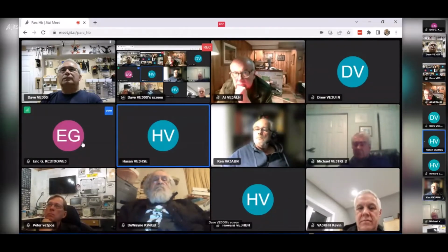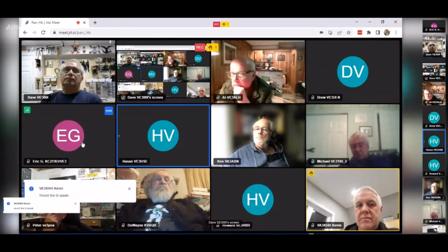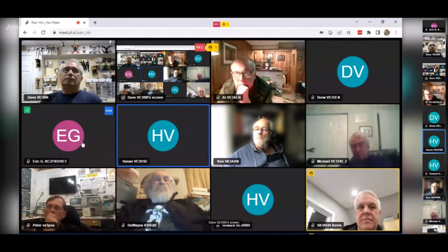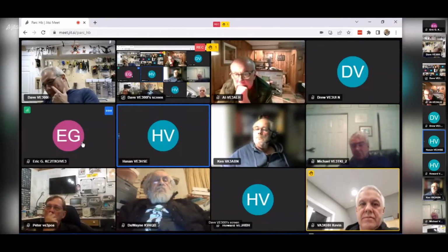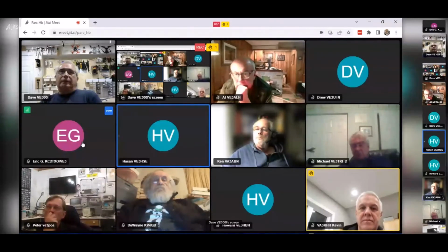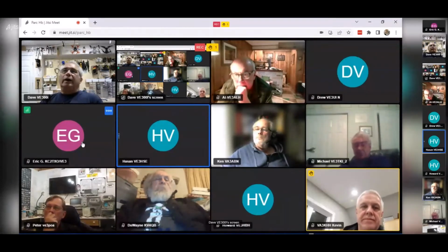And so maybe you're just pulsing it too fast, and it's burning power in the drivers. If you used, like, I don't know, 1,000 steps per second, that might have been good enough. You would have got the same result, but a lot less power, and probably would have been better overall. I think the problem is that we're pulsing too fast, maybe.